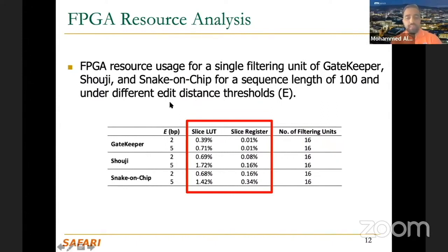And these are the results for FPGA resources. So this is the number of lookup tables needed. You can see most of the cases is less than 1 or less than 2% at most. And that is a very cheap algorithm to be implemented in FPGAs. And since it's very lightweight with a very low resource footprint, then you can use a large number of replications. So instead of solving a single problem, you can have 50 problems, for example, or 100 problems if the utilization is less than 1%.